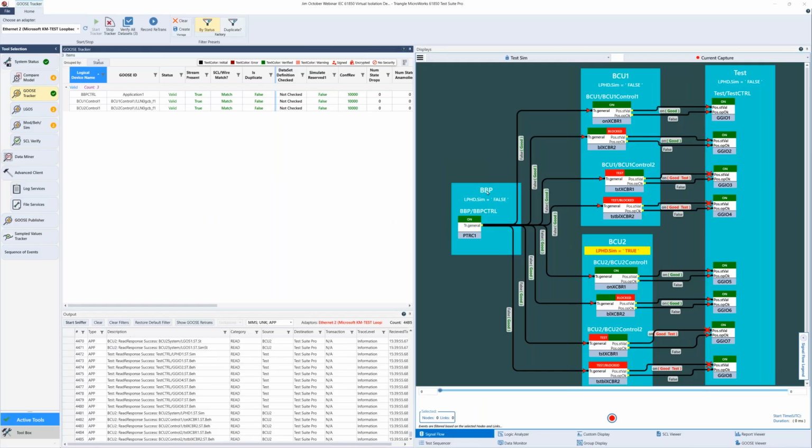We have a busbar protection that we assume sends out a trip, and then you have a bunch of bay control units, two of them, and in each of them we have four logical nodes for circuit breakers. We just want to illustrate a little bit how the reaction is when you receive a trip from the busbar protection, and the different logical nodes here are in different modes.